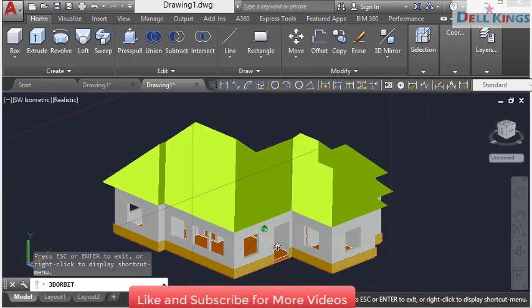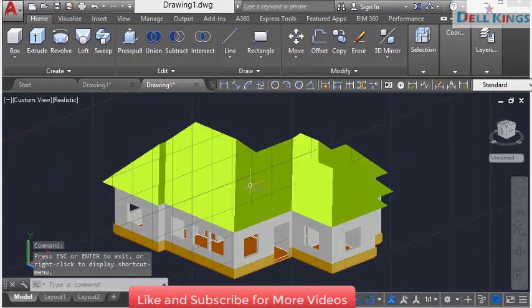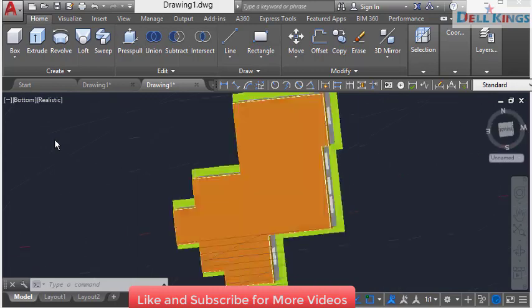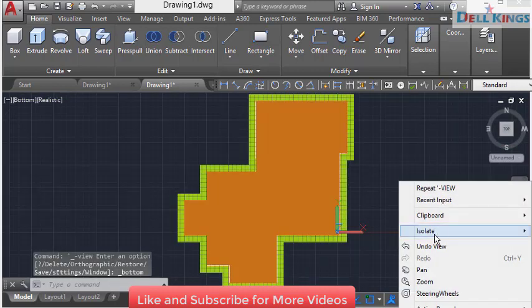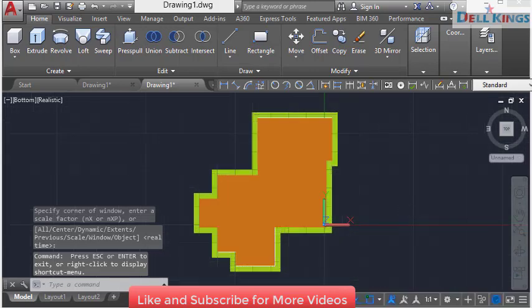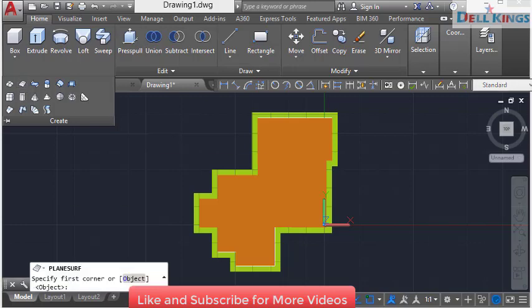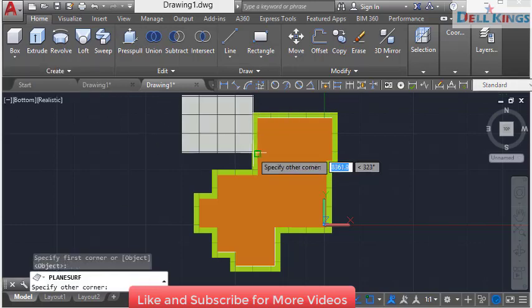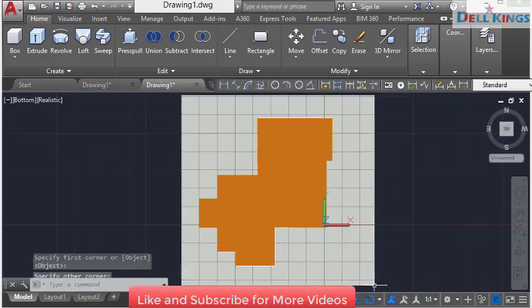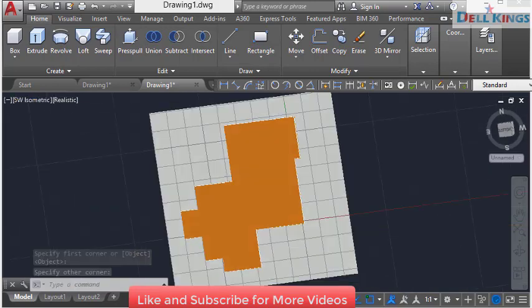So what we are left with to do now is to create the floor, the outer floor. So go to custom view and change to bottom, and we are now going to zoom, select zoom and zoom inside and press enter, and now go to create and select surface. At this point we're going to click and come this way, draw this way to get the surface and press enter. Now go back to southwest isometric view.